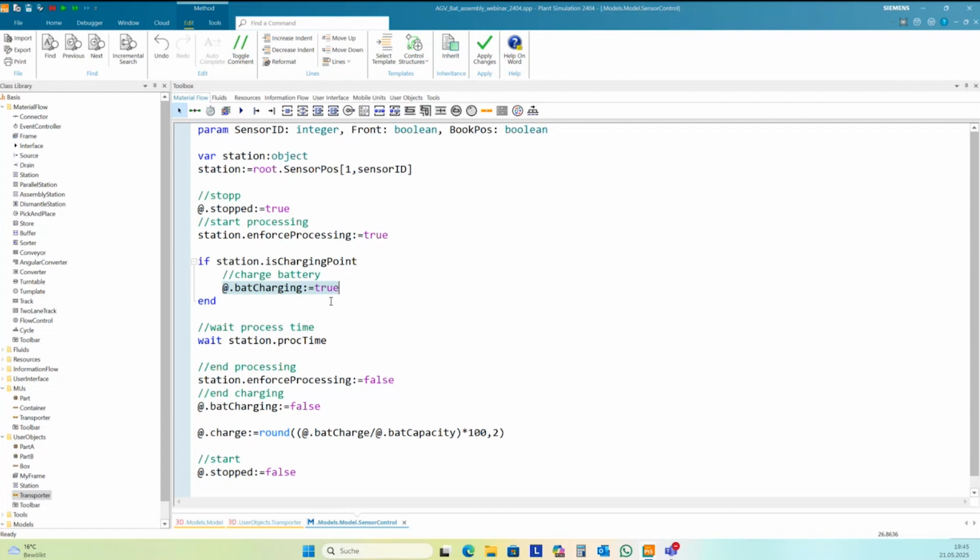If you have, for instance, a single station and you want to cut this part into 10 parts, then you need an element in Plant Simulation that can hold 10 parts. So you need to combine, for instance, a single station with a buffer. But then you can do this, yes, without any problems.